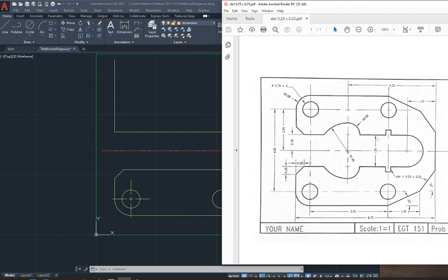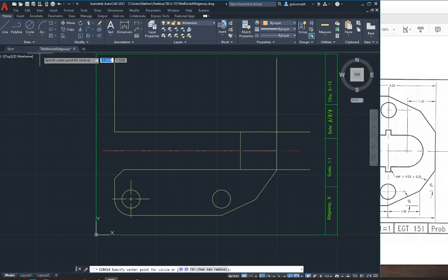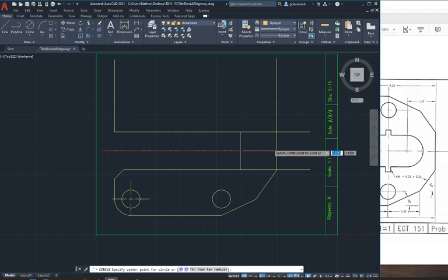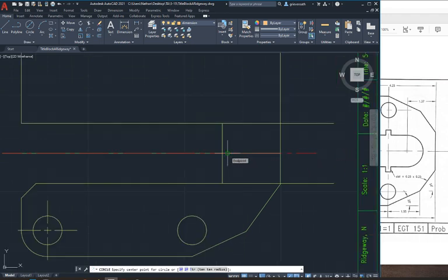And then we know that all the way across will be 1.56. So we'll go over here, and I guess we can just use the diameter tool. 1.56 will be our diameter, and our center is that endpoint where we just drew. So we'll select here, and then, what did I say that was? Such a short memory, 1.56,